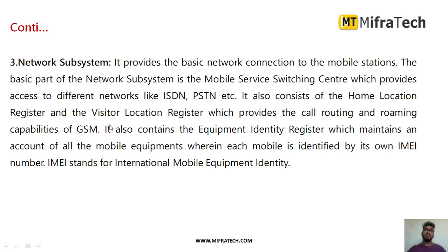The basic part of this network subsystem is the mobile services switching center. It provides access to different networks like ISDN or PSTN, etc. It also consists of the home location register and the visitor location register, which provide the call routing and roaming capabilities of GSM.